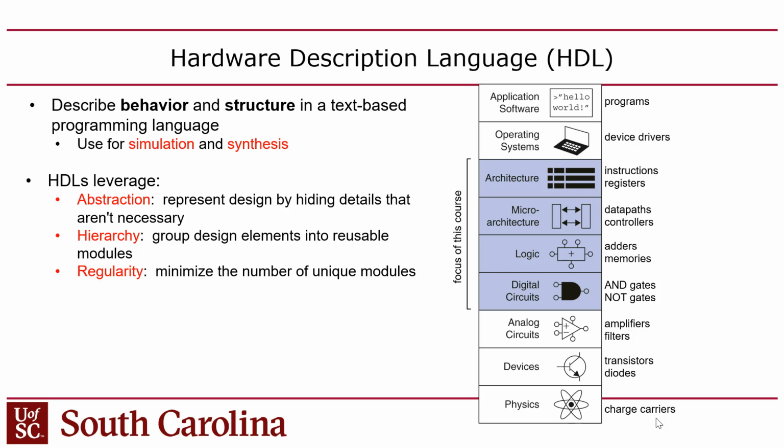And then synthesis is the process I described on the previous slide, where you take the HDL and lower its abstraction down into the netlist level where it's gates and wires, and then down again where it is still a netlist, but now everything in that netlist can be directly put on the FPGA in a primitive on the FPGA. And then you deploy it on the FPGA or an ASIC. You can also do this on a chip too. You can generate designs that would go on a chip that you send out for fabrication as well. Of course, in this class, we're using an FPGA.